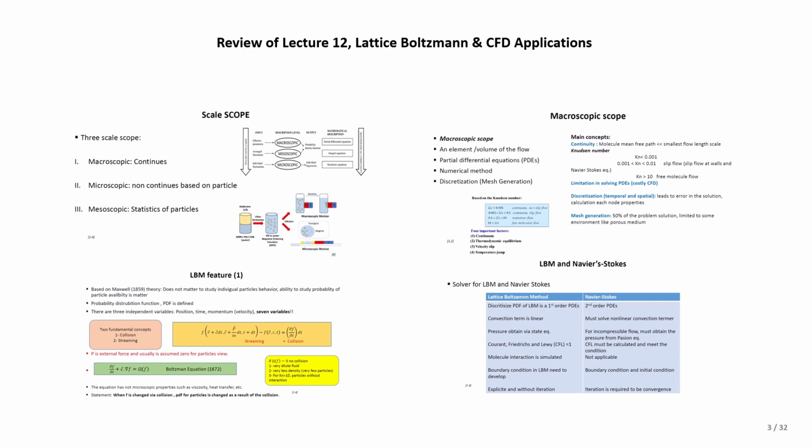It's working very well. However, lattice Boltzmann is still in development, and much research is going on this method to make it much more applicable. For example, in turbulent flow applications, one of the matters that needs to be resolved in every lattice Boltzmann simulation is the viscosity, which is a complex term, especially when we are working with high Reynolds number. For the larger scale, the concept says